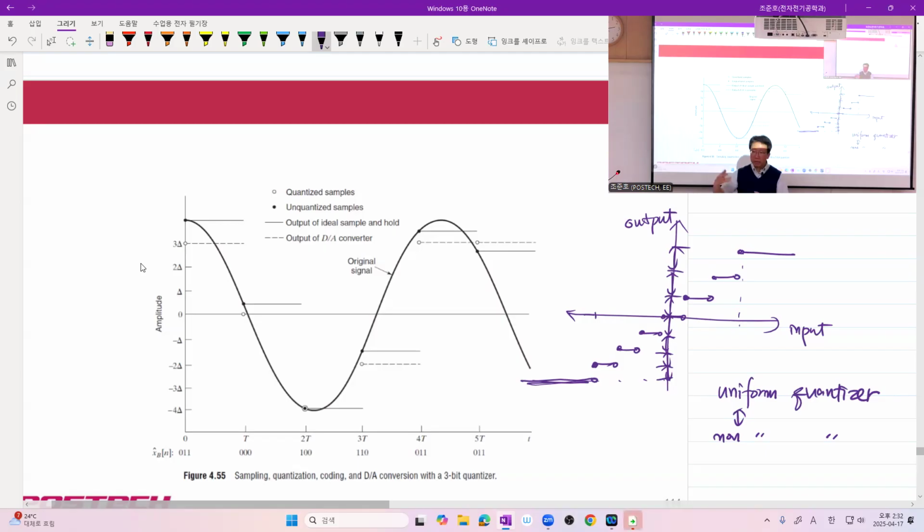Actually, if you have seen some introductory digital communications textbook for undergraduates, there is mu-law, A-law, something like that, to convert our digitized speech signal to some finite length bits. And people have drawn some histogram of our sampled voice signal, and they have found that in the low amplitude part, we'd better assign more bits, something like that. Got it? But anyway, so this is the first thing.